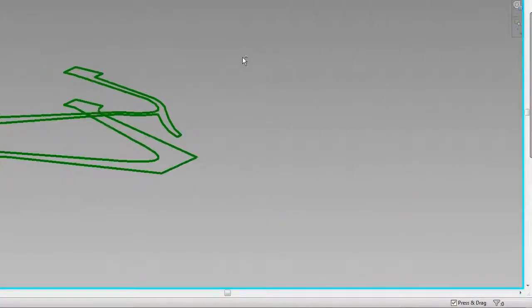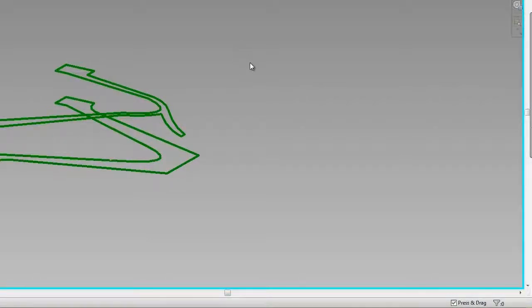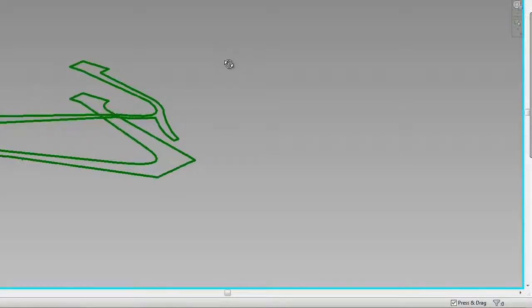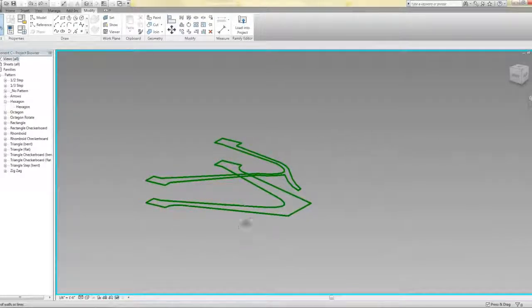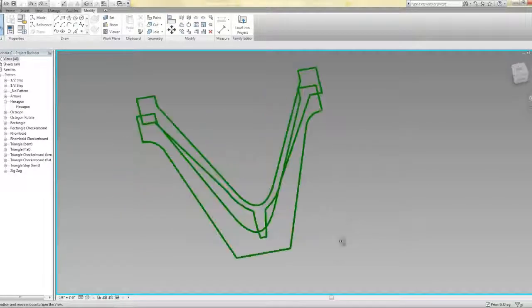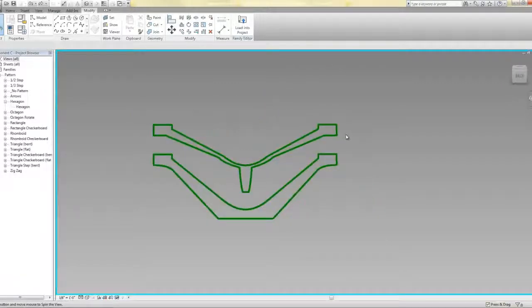So what we've done here is we're working in a curtain panel pattern-based family. And this family lets us use control points to instantiate a pattern we build in this environment onto a curtain panel system. To simplify this attempt compared to the last attempt, I focused on using two rail curves as the basis for a solid geometry.